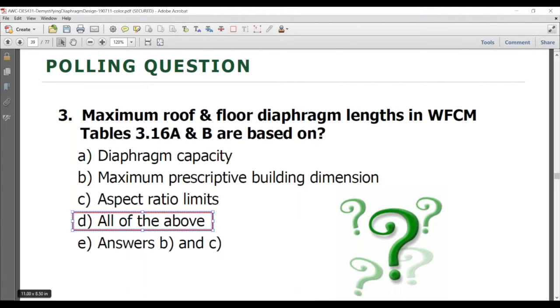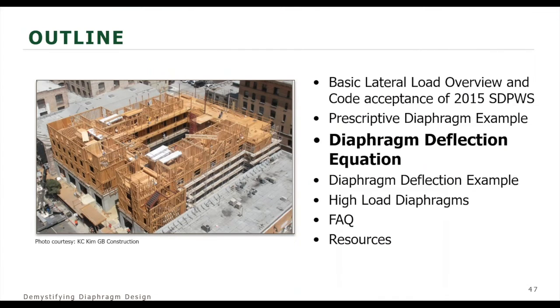And while we're making that transition, let me just share, some of you may be asking about deflection calcs. So I mentioned that we're just using the wood frame construction manual based on a strength approach, a capacity approach. It's allowable stress design, but we're not looking at deflection calcs. And the reason we don't do that is twofold. One, for most wind design applications, deflection or drift limits aren't required. For residential applications, it's not required for either wind or seismic.